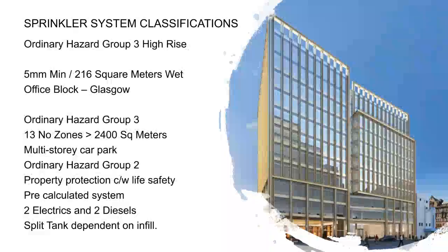Okay, it was a pre-calculated system, 2 electrics and 2 diesels, split tank. Now, when I say 2 electric, 2 diesels, that was actually multi-stage pumps, which is what you need to do in 45 metre systems and above.